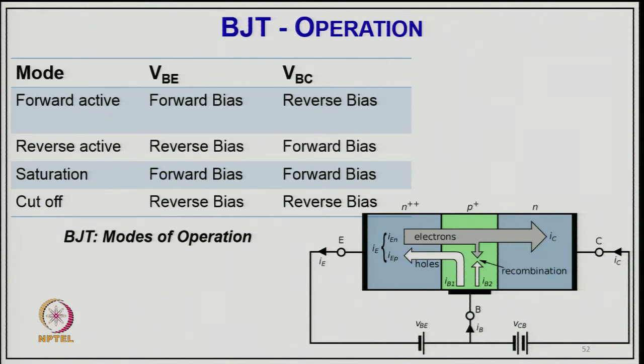It depends on the application. In some applications, as I told you, we might be using it as a switch, operating it in saturation and cutoff, but for amplification we will typically be operating in the active region.